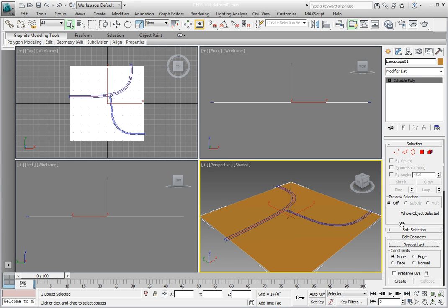We're going to go ahead and change our selection method so that we can use a tool later on in our editing process. In the main toolbar, make sure you're in Select Object mode. Currently, we're selecting our object using a rectangular selection region. Click and hold on the rectangular selection region, and all the way down at the bottom of the flyout, you'll see a spray can. This option allows us to select by painting. This selection method is an alternative method we can use to edit our geometry. Release the mouse button to make the change.